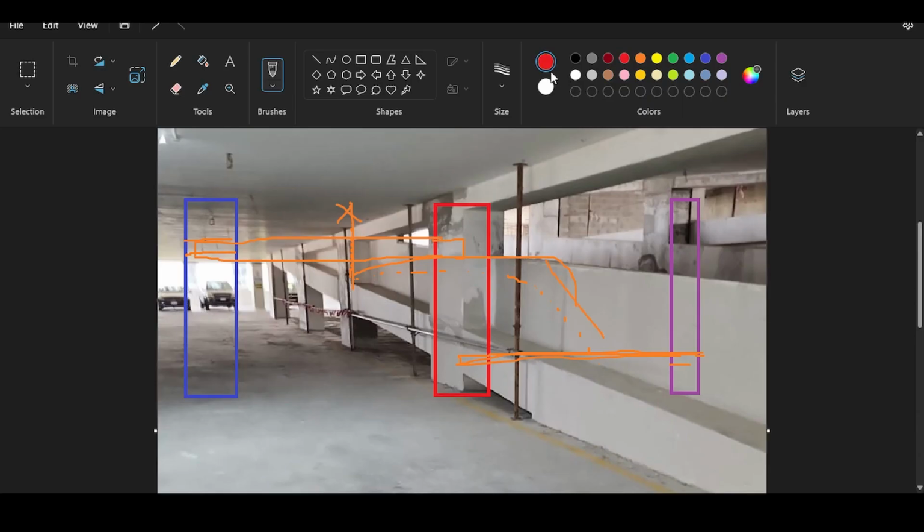Remember, this is a suggestion from me to you. Different regions have different construction practices. So what I would do is I would construct this part and then basically construct this part together. And by this part, I mean this part repetitively, because there are multiple columns at different heights. You get the idea. And then cast this ramp.